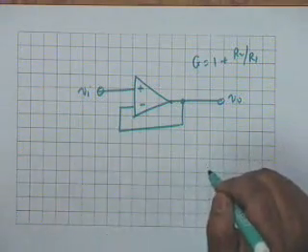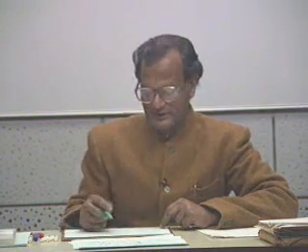You might ask, why should we get a circuit with a gain of +1? Well, it provides isolation. So if we apply a voltage source here, then the output and input are isolated, because this voltage source does not deliver any current, but you are transferring the voltage source here. It's actually a transfer from input to output, and the two sources then become isolated with respect to each other.